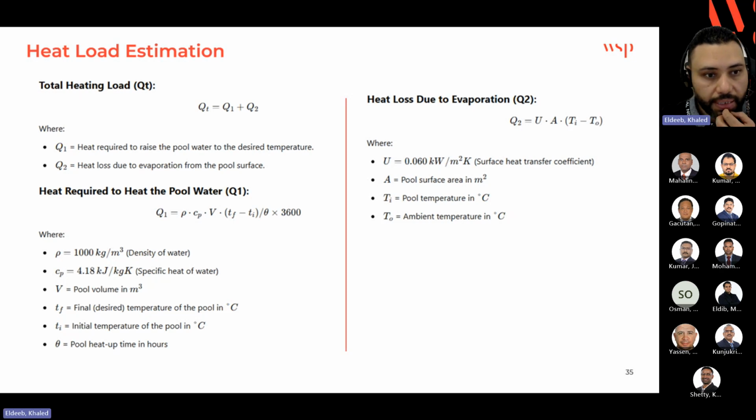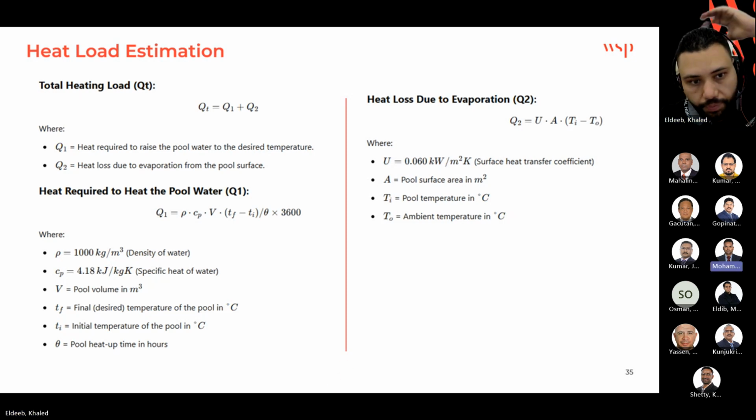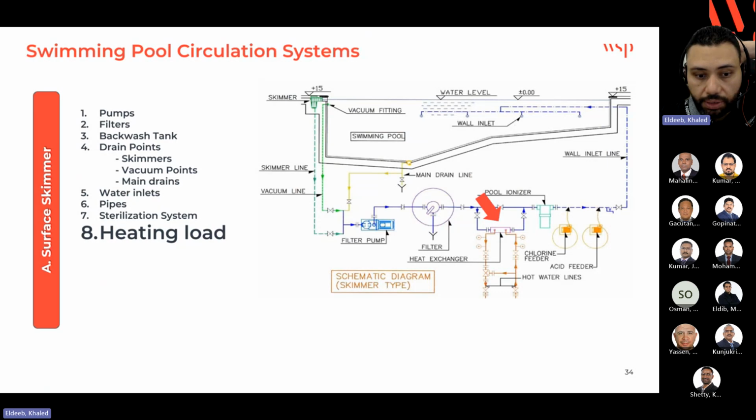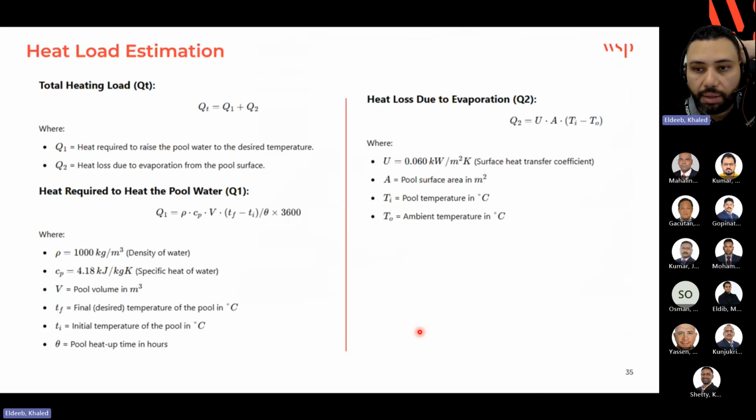There are many sources to get this temperature, Zubair. Like here in Dubai, we have the Dubai recommendation, which could be used as a reference. You mean the filling water temperature? Yes, the filling water temperature, the raw water coming from the regular domestic tank. I have a project here where the source of water is Dubai Municipality. I know the temperature from the network is around 20, maybe 18.